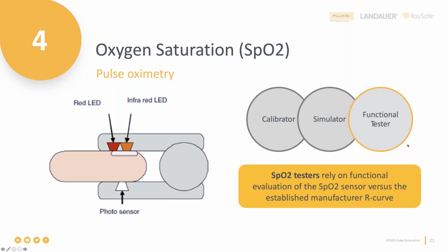This is red and infrared light that's shown in succession, and the tester, which will take the place of the finger in the diagram there, will measure the amount of light coming in, and decide if it's red or infrared. It will then calculate how much light would be shining through an actual finger at those settings. And then it turns on its own LED on the bottom so that it looks like light actually was shining